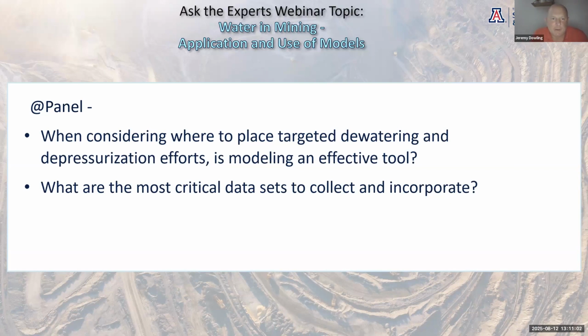It's obviously a very case-specific question, right? Every site is different. But in most bedrock or deposit settings, most of the groundwater flow and occurrence is within the major structures or discrete fracture sets that are preferentially more conductive than the general rock mass. So, at least for general dewatering purposes, to remove water volume from the mine and lower groundwater levels, you usually need to place the dewatering pumping wells into those discrete fractures.